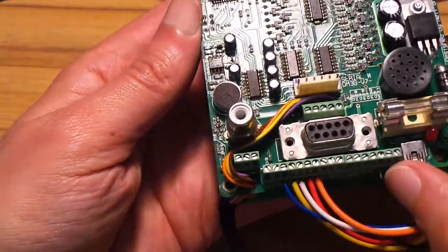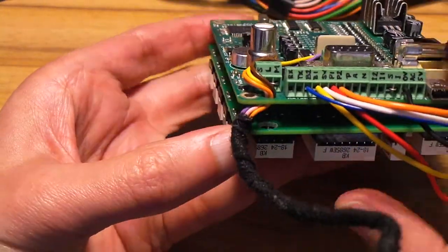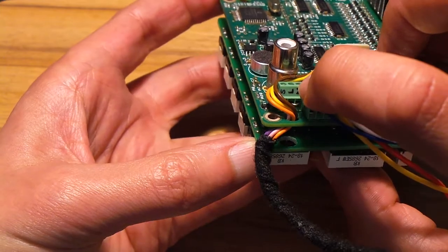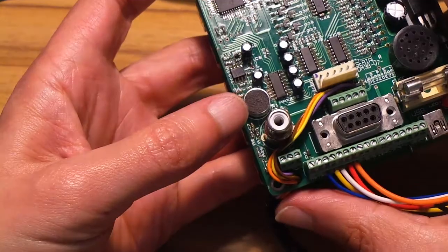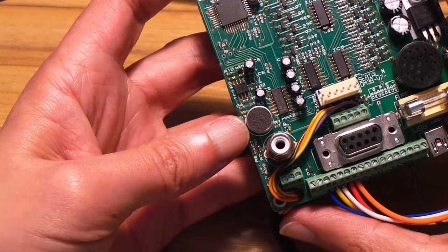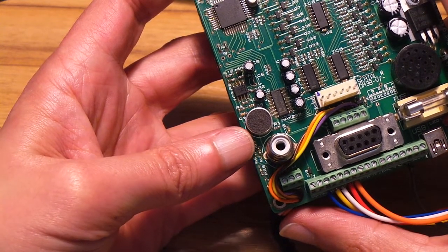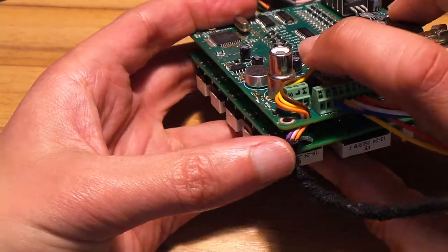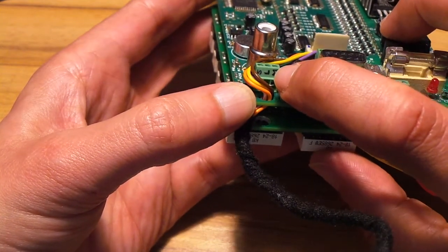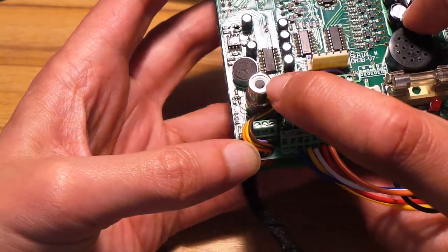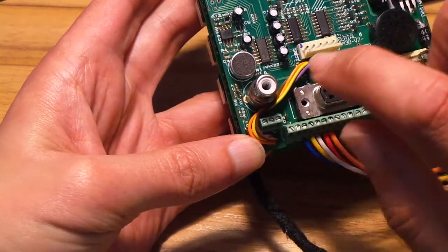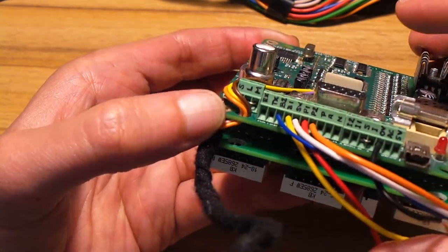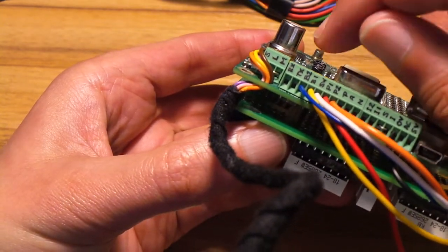There's another wire link between the pins marked L, which is line input, and M, which is the microphone amplifier output on here, to enable us to use the onboard microphone for the audio input to the voice display. If, on the other hand, you prefer to use a connection from, for example, a car stereo, then you'll need to remove this link between pins L and M and put the audio connection from the car stereo in via this phono RCA plug.